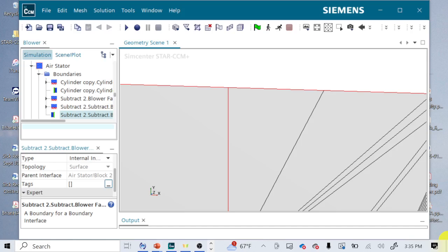Changing it into a wall will stop the flow, if, theoretically, it wasn't connected at all. But at that point, you've already failed because they're not connected at all. So the thing is, if only a little tiny piece of it is a wall, that's not a problem. It's the equivalent of having a bump on the surface instead of having a hole just venting to atmosphere. So it is still kind of a problem if some of those cells don't imprint properly, but it's more of a problem if they're an outlet.